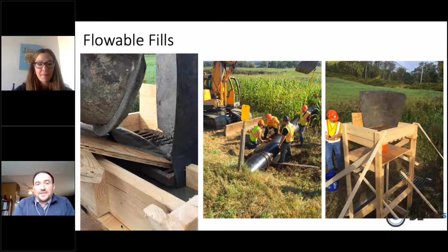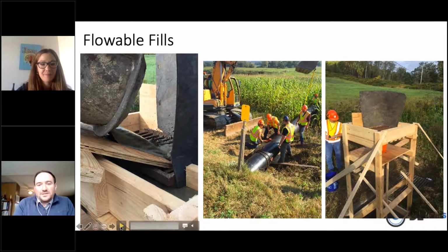Yeah, to give some context here, folks, this is a New York State DOT project, where that's me in the blue helmet and the hard hat in the center page, showing some New York DOT folks how to install Snap-Tite, which is a solid wall HDPE, terrific for lining culverts. This particular one was a beautiful day in the middle of farm country, upstate New York. And this was 32-inch Snap-Tite going inside of a 36-inch CMP. What they did, and I learned a boatload from contractors, as I'm sure you do as well, Cassie, is they